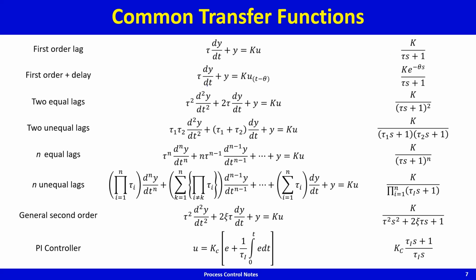Okay, this is also pretty straightforward. You have the input u. It is delayed by theta time units. This delayed thing goes into an ODE, into a transfer function of the type k by tau s plus 1, and then you get out y.